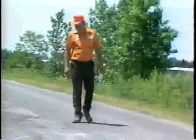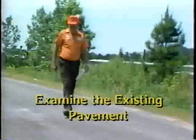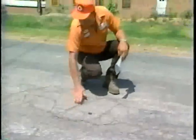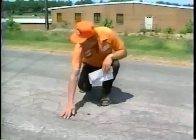The first step in the 7-step procedure is to examine the existing pavement. This examination is done to determine whether a seal would be a suitable maintenance activity for the pavement distresses present. Seals are not effective on extensive structural failures, such as severe cracking and rutting, but are effective in treating the following distress conditions.